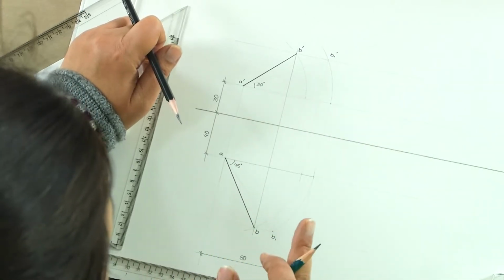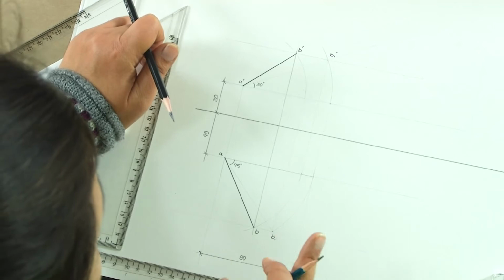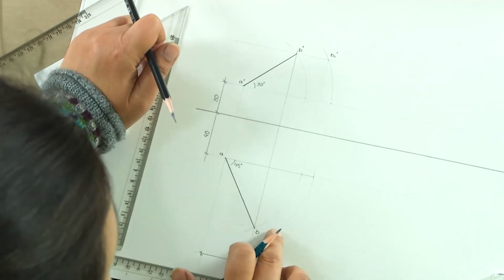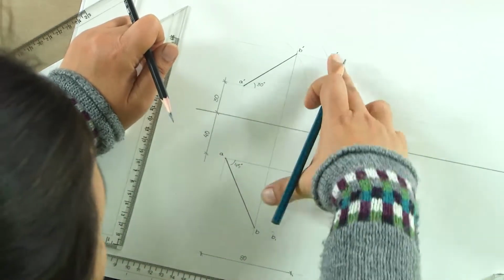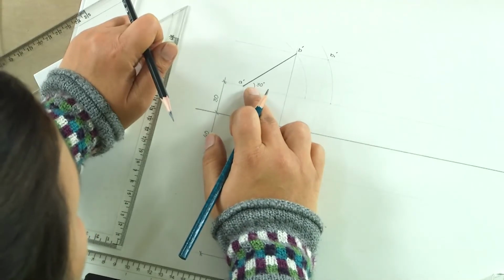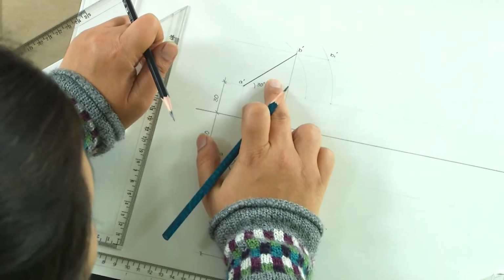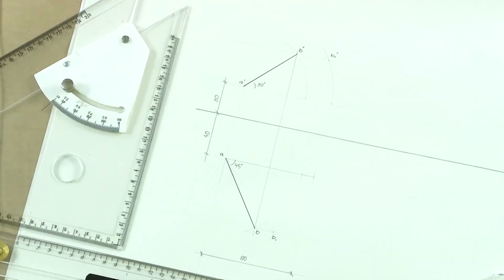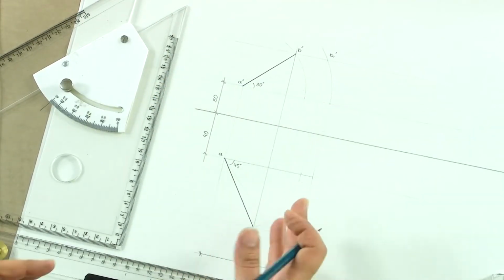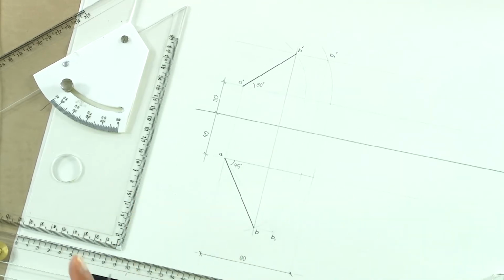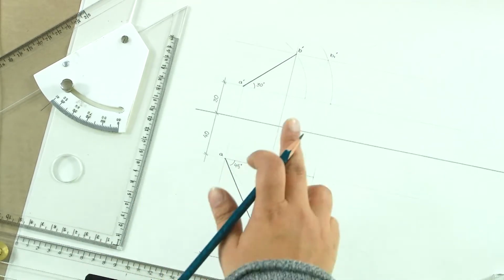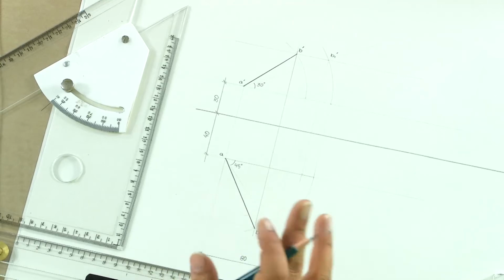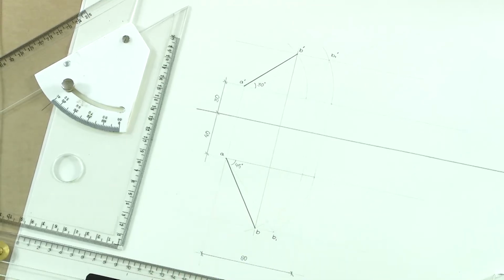And then we will draw the true length of the line. If the true length of the line is given to us, we will draw the true length of the line in both the places, and then we will calculate the true angle that the line makes with VP and HP. So, that is what we can do in order to calculate in reverse the angles that the lines make. Now, where would this be necessary?